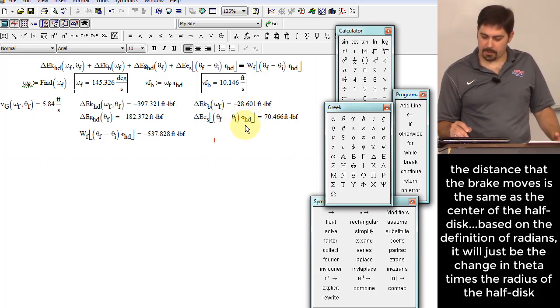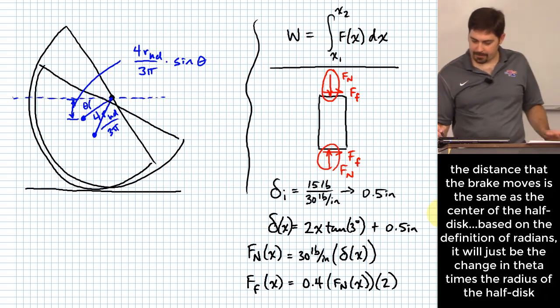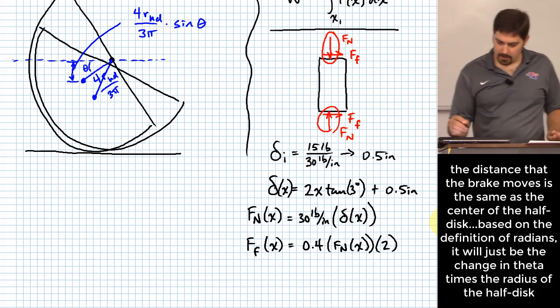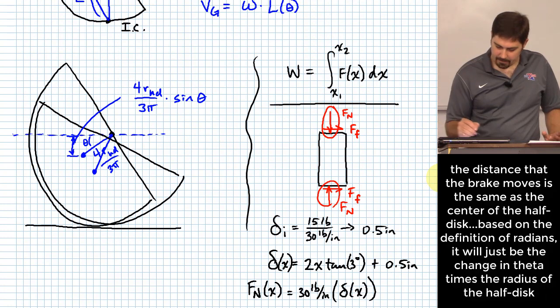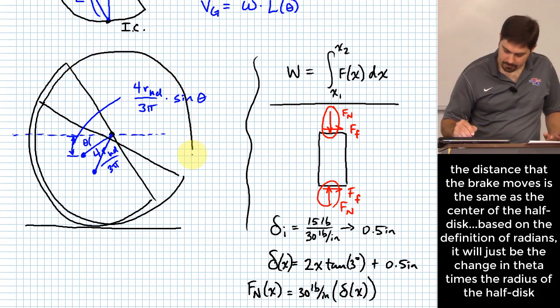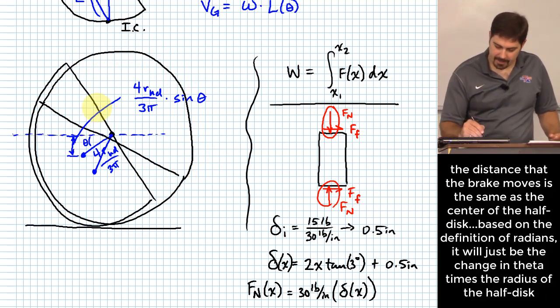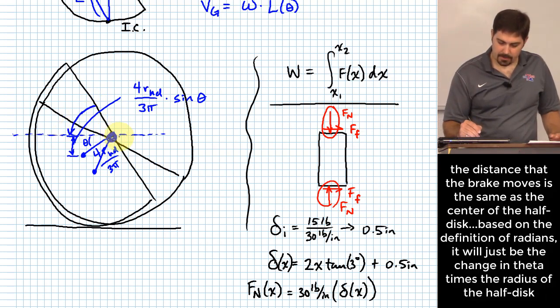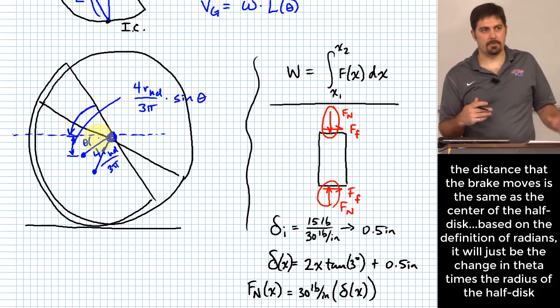What I put in there is equivalent to x, so that's probably worthwhile going back and showing here that as this body rolls, right, you would know what to do if this was a full circle, right? It wouldn't be confusing to you that if this thing moved by theta, right, that the center of it would move by theta times r, the radius of the wheel.